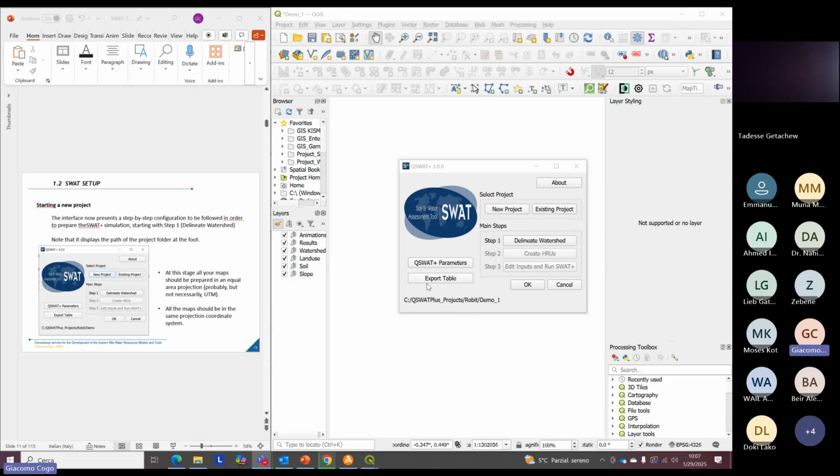And just a note, in general, since we have to put many different maps and files, like shapefiles or raster files, as in many projects, we will need to set the same projection coordinate. In this case, we already have these prepared files, but if you have to create a new project, please remember to use files with the same coordinate system.